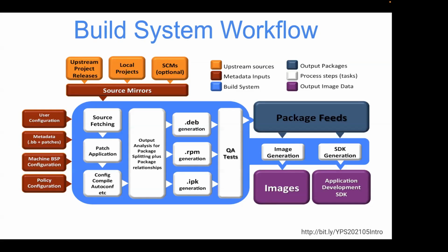From that, there's a second set of recipes, I should say, that can be used for doing at least these two things. The first one is image generation: which packages are put together in order to make a particular image. And there are extra steps that can potentially come along here, things like WIC and others, in order to build an image that will go on the target. Minimally, the image will include things like a kernel, perhaps a bootloader, the root file system, maybe a device tree file, and so on. Maximally, if they go through WIC, there will be a binary image that you can put directly onto the storage device on your embedded target. So there are a number of different ways through image generation that will give you the pieces you need to go onto your eventual target.